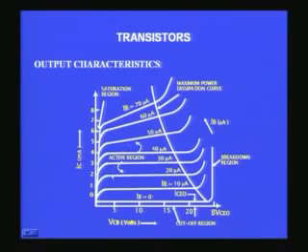Now, this is actually the basis under which you will design your circuit. So, it is like a map for a given device. The characteristics is such an essential part of the design that you have to have a clear understanding of the transistor characteristics to really make use of them. And I mentioned to you that it is like a map, and if you want the transistor to operate in a particular way, you have to fix the operating point of the transistor circuit somewhere in this region.